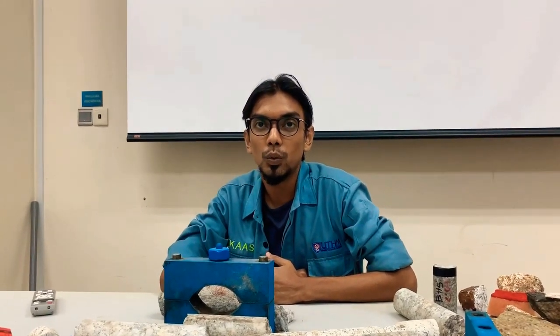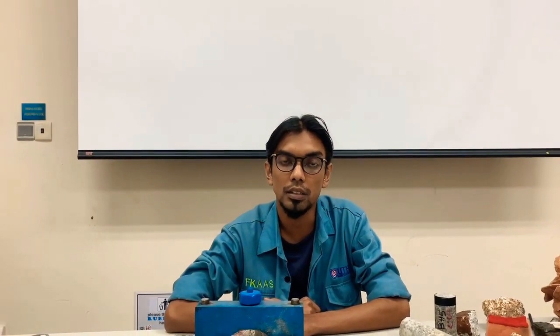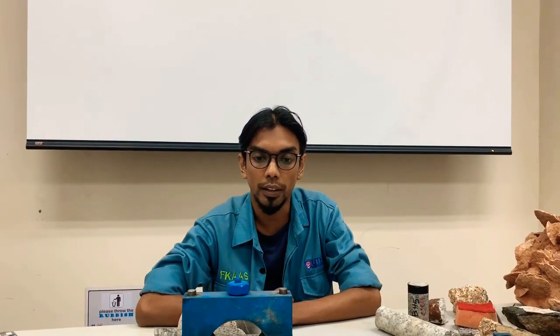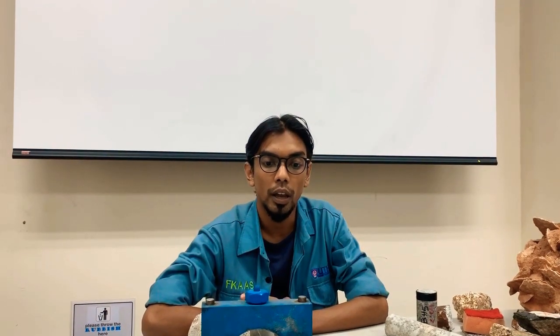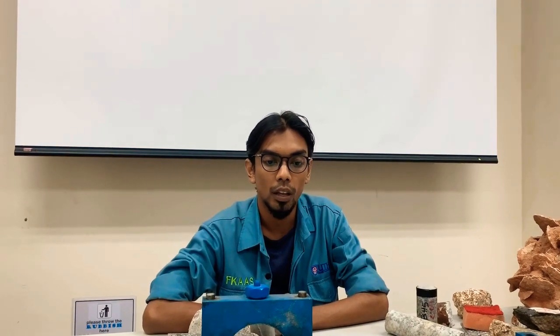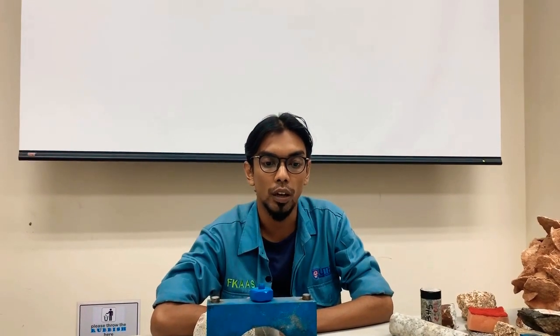There are two major techniques for stabilization and solidification treatment for soil: in situ and ex situ. Ex situ involves a method that includes excavation of the soil and its transfer to another location, either on or off the site, for mixing with the stabilization agent. In situ involves mixing the binder or reagent into the soil at the place where the soil is found, or its original place, without transfer and excavation procedures.